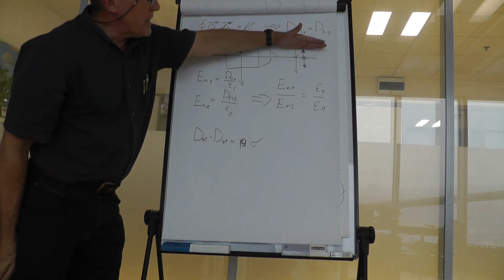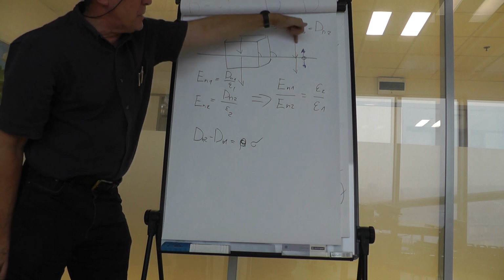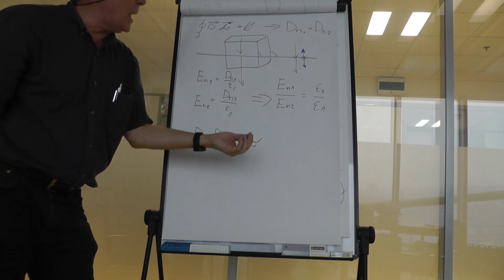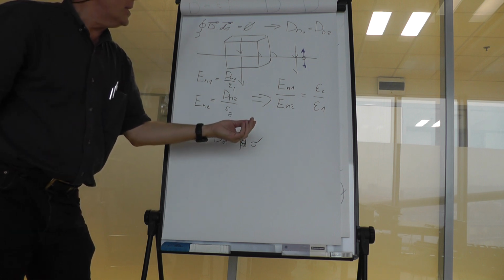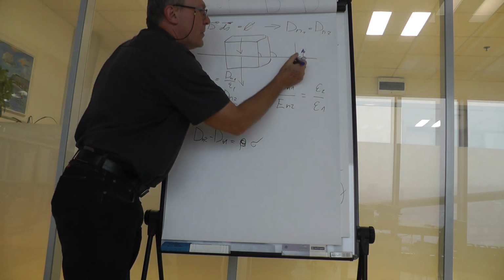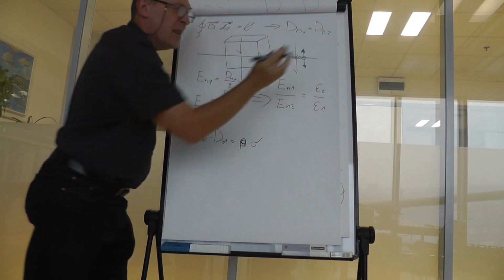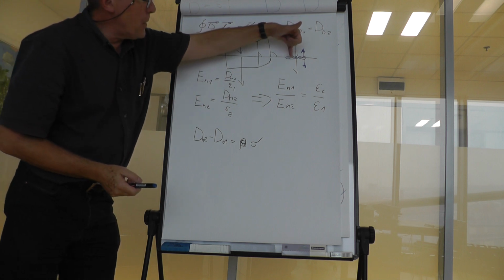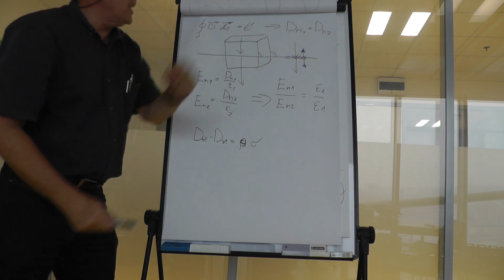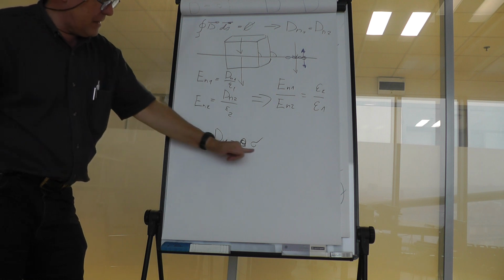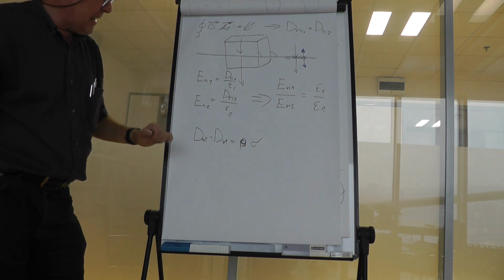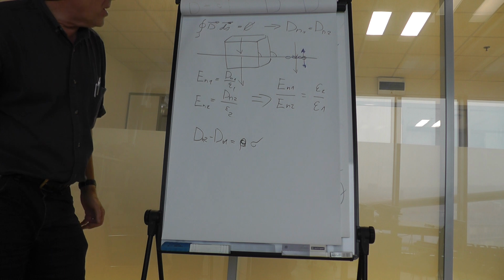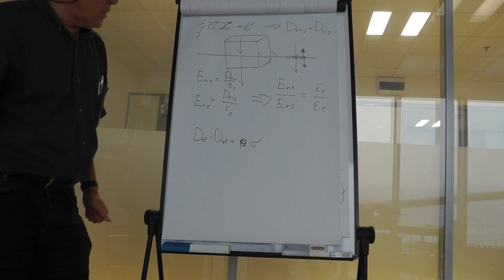Now, upstairs, the field is subtracted from the incoming one. Downstairs, the field is added to the original one. And therefore, if we have a number of those charges all over the plane, we know that the difference between those two must be the charge, which is again the same equation. The charge density is the difference between those values of normal flux density components.